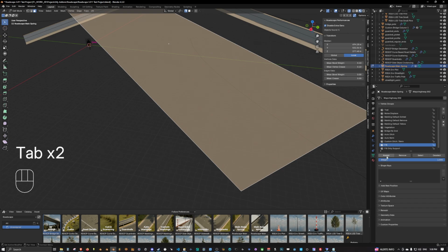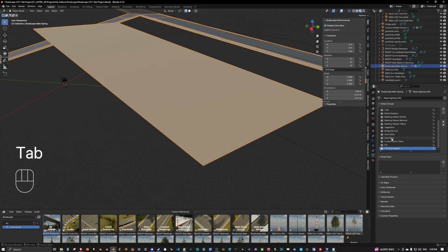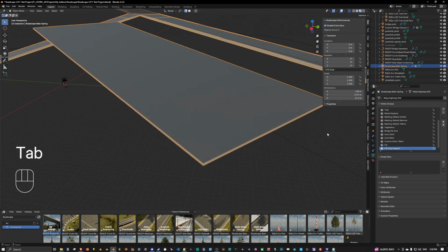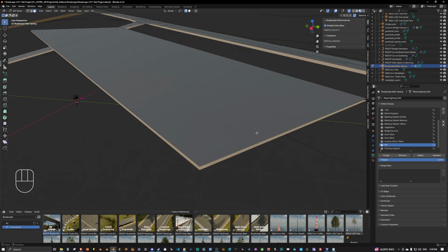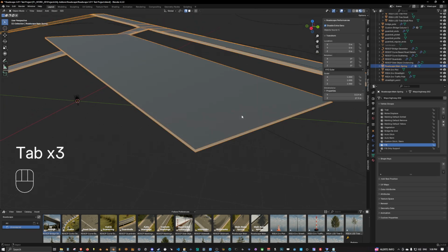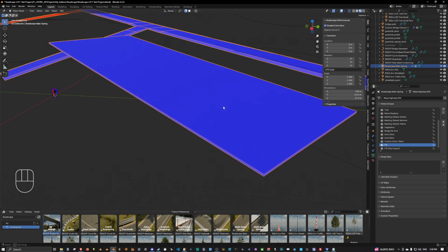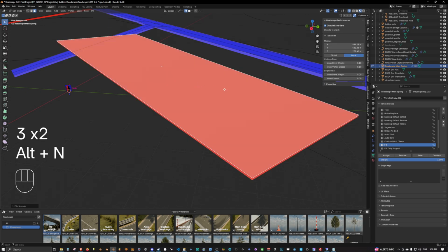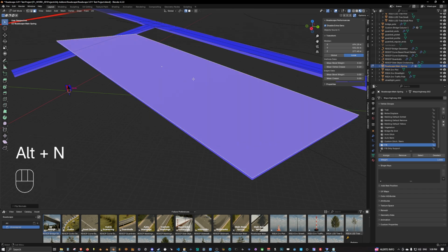If we were to have fill and then fill only support, it will only generate support. Okay, then you can remove fill only support, and if you have only fill, it will generate both. So once we have done this, we need to check the orientation of the normals. So this is good. Sometimes it can be inverted, so sometimes it can generate like this. So you want to do Alt N and flip the face.